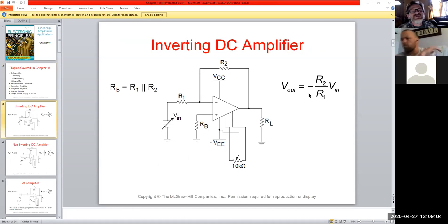And then on the left, we see a formula that gives what our total resistance would be. Remember that with op-amps, we always have a virtual ground point. Ideally the input resistance is infinite, so it would be an actual ground. Realistically, depending on the device, it's a very high megohm range. Because of that, these two resistors will be in parallel and set the value of this one to have a balanced circuit.